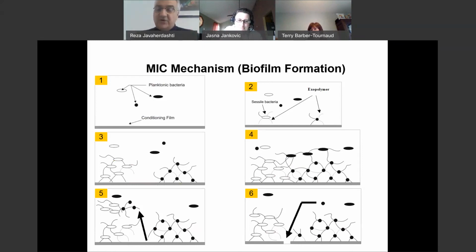Therefore, the pitting, the enhanced corrosion, is to happen under where you have low oxygen pressure. In other words, in step 6, the arrow must have moved to show the pitting under the biofilm to the right side, not where high oxygen pressure exists.